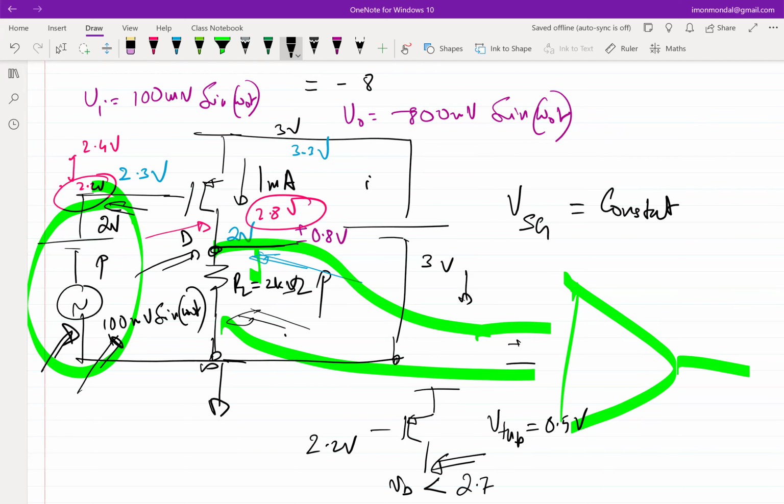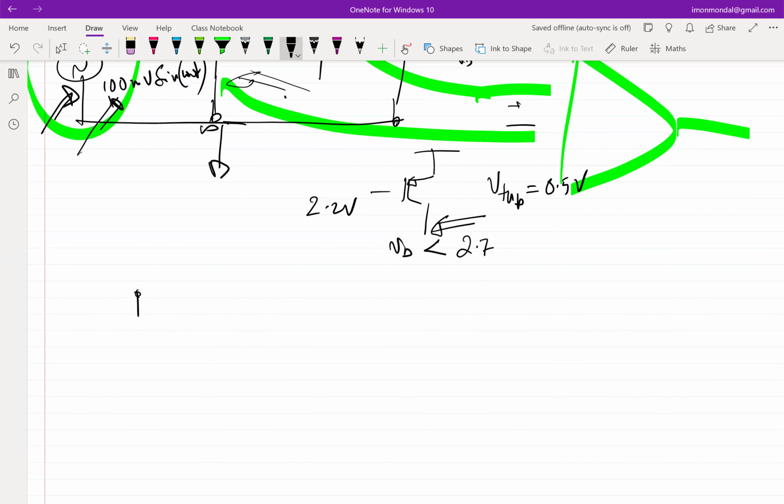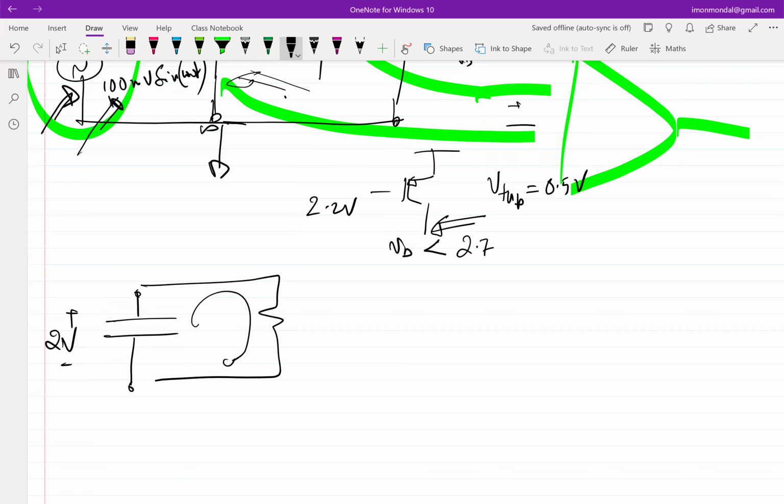Okay. So again, if I take you back probably to lecture 3 or 4, we discussed something about a capacitor. So if I keep a capacitor and charge it to, let's say, 1 volt, or in this case, let's say 2 volt, can this capacitor behave like a battery? Yes, but there is a caveat. Under what condition? It doesn't discharge, essentially, right? I mean, you don't load the capacitor with anything else. So if you load it, then it will eventually discharge, and then it's no longer a battery. If you don't load it, then it's a battery.